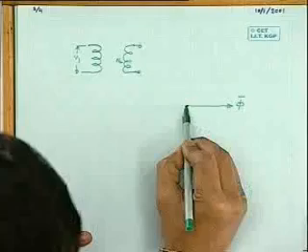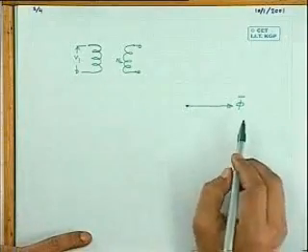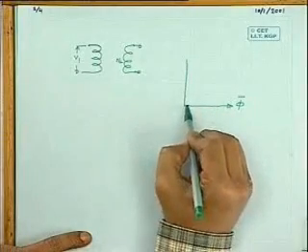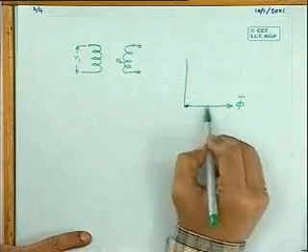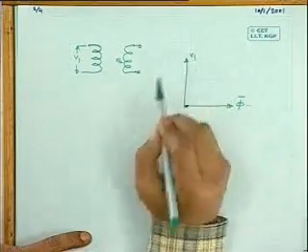So if that disturbs you, you can always think mu_r is very large and it draws a very small current to establish this flux. Therefore, the applied voltage is here. So this small current or vanishingly zero current is required to establish this flux, and this is the applied voltage V1.